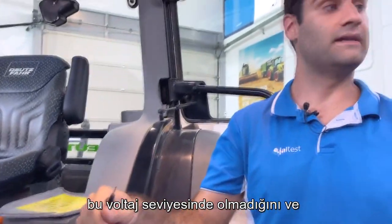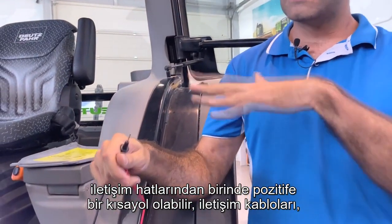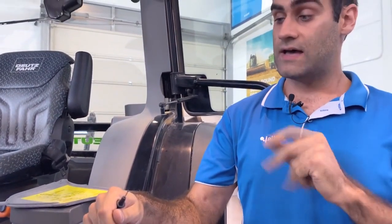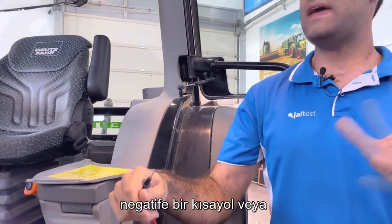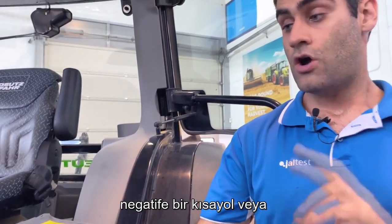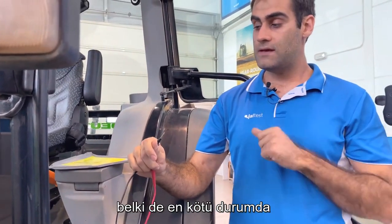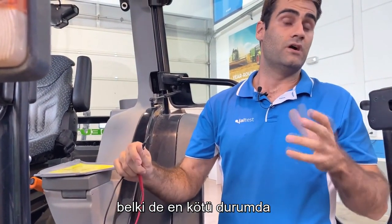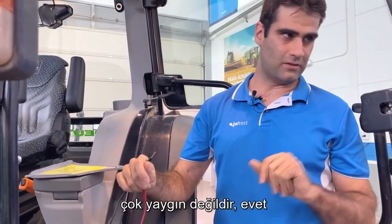If we find that CAN lines after switching on are not in this voltage level and it's in an upper level, we may have a shortcut to positive. In one of the communication lines, communication wires, we have a shortcut to positive. If it's close to 0, we may have a shortcut to negative, or maybe an open circuit, or maybe the worst case, we've got the CAN driver faulty, but that's not very common.